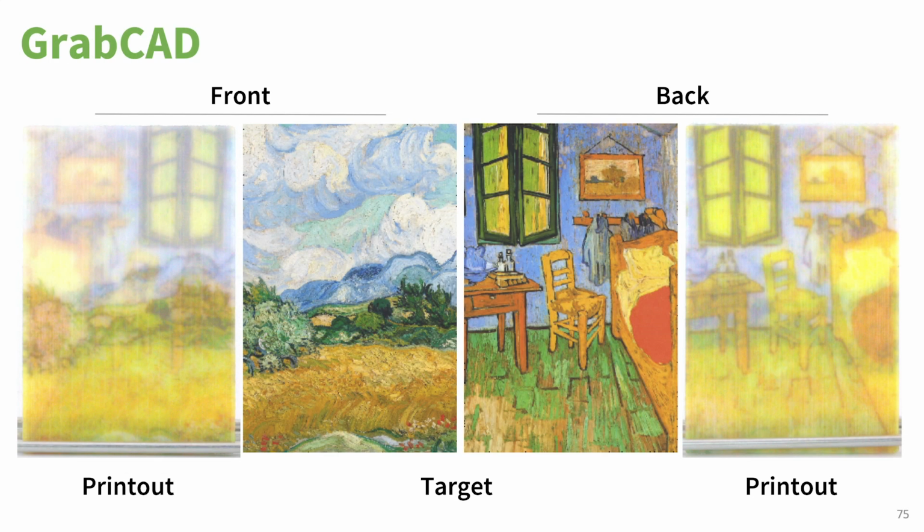And this is what happens if you just take a 3D model textured in this way and send it to the default printer. Essentially, because of this translucency, the texture from one side will completely creep to the other side, and you will totally lose the notion of what you should be seeing on this side in the first place, right? I remind you, this is what we would like to be seeing here, and this is what actually comes out as we print it out.